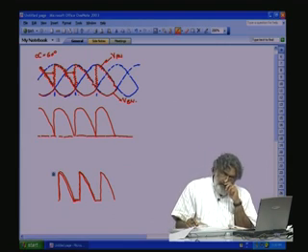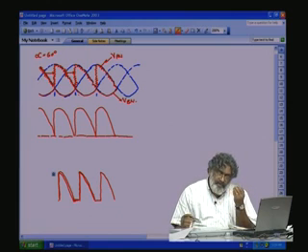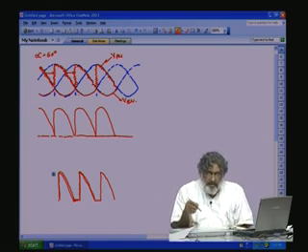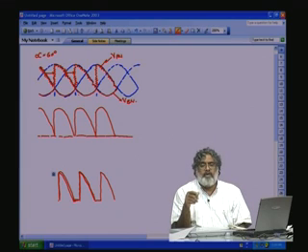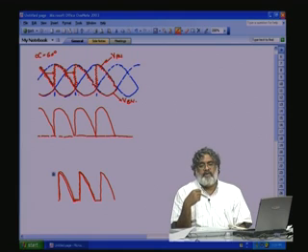Now, why have we come to the semi-converter? In many drive applications we may not require the output voltage to be negative. We want only a voltage control from 0 to positive. Then we need not use thyristors everywhere, because with thyristors and alpha control, we can have 0 to positive voltage. But the problem is, with thyristors we again require extra gate drive circuits, so it is expensive. Instead of that, we can do away with a diode.